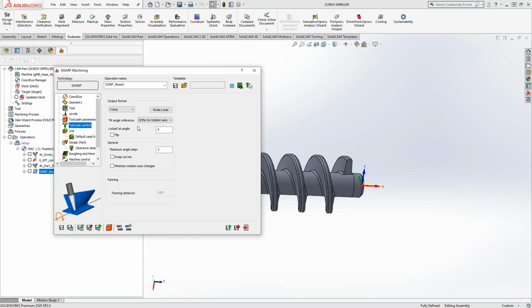And then in the tool axis control, I really just had to tell it how to tilt. But I only have two options there. So this is automatically generating a Swarf machining, Swarf cut style toolpath. Like I mentioned yesterday, it's very bare bones. There's very few parameters here to play with because this is specifically for this type of thing.